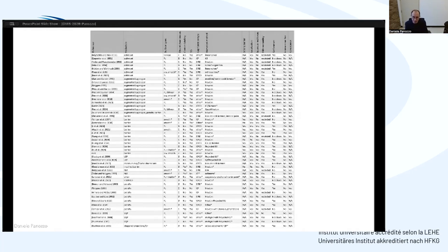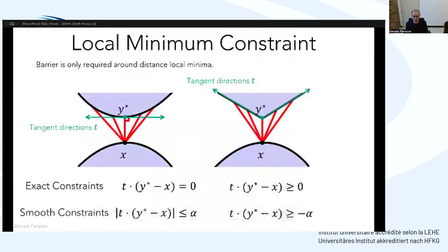So we ended up re-deriving from scratch a continuous potential, which allows for a discretization that satisfies all of these properties. The construction is quite involved, but the key idea is simple: if you take a point and you want to evaluate the potential at this point, what you really care about is the distance to local minima of the distance function to any other surface or itself.